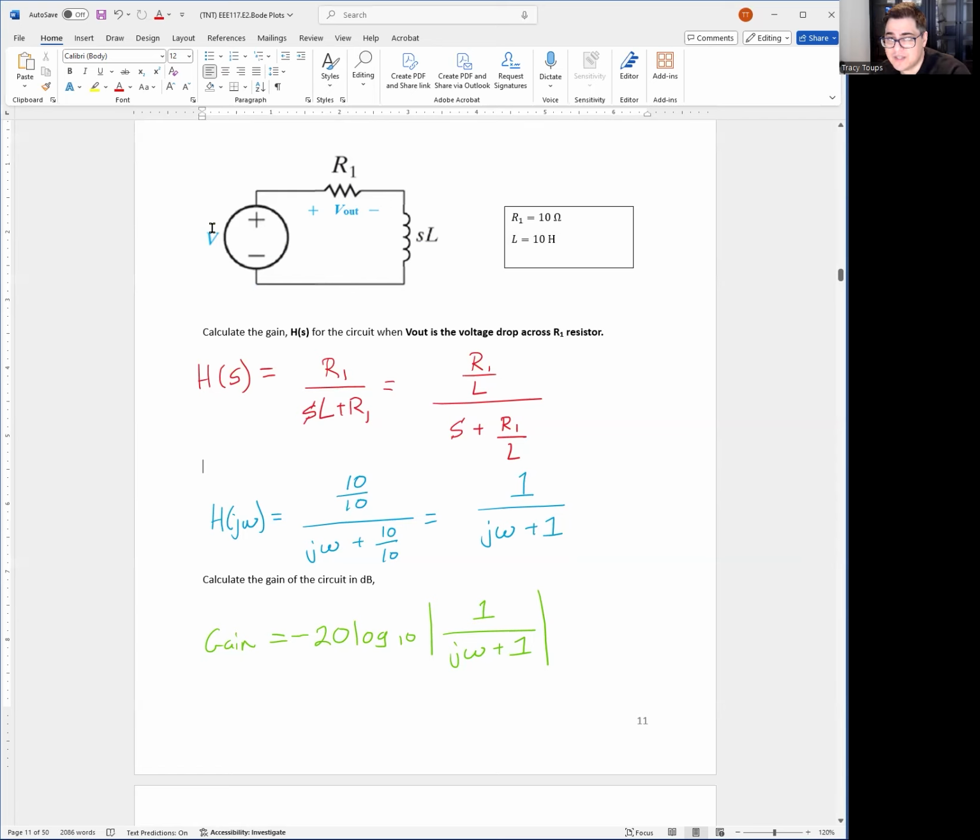So in this case, your input voltage goes almost all to the resistor, none of it to the inductor. So you're passing the signal through. If this is 50 volts, this will be almost 50 volts. It'll be like 49 point something volts. So you're passing the whole signal through. Because you have a low frequency, the inductor doesn't do anything.